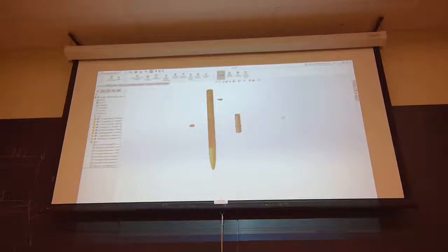It doesn't really matter, but we're going to have to. On the outside. No, you don't want that to be disconnected. Go ahead and hit concentric, because you want them to have the same center. It's the other stuff, this way, axial, distance. So hit OK first. You need to make another mate. So top face. No, top face. The ring. The outside of the ring.